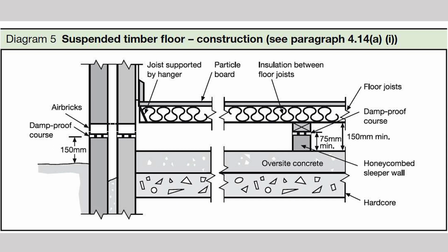You have got traditional, and I use the term loosely, traditional suspended timber floors. That's where you would have what we would talk about as honeycomb sleeper walls. So you'd put down a simple oversite concrete, and then you provide ventilation to that timber floor.